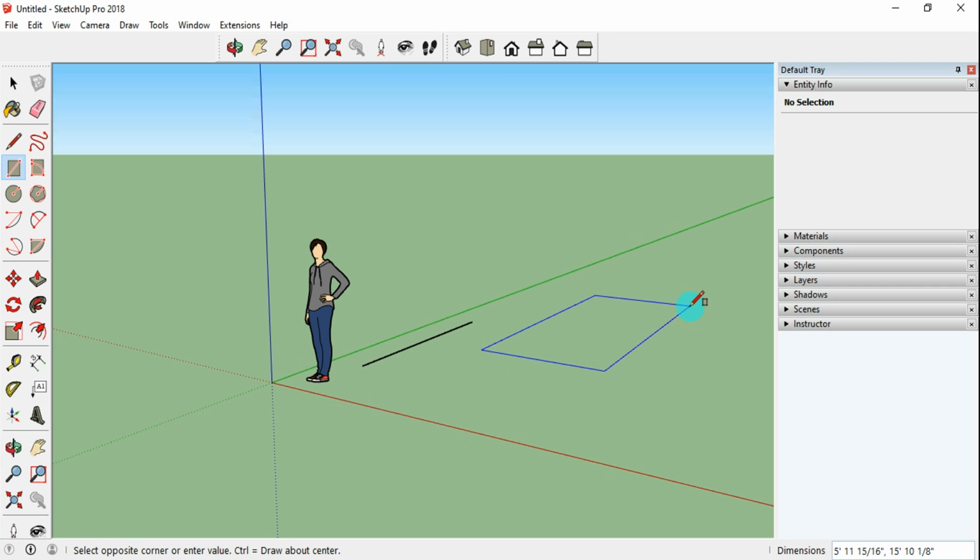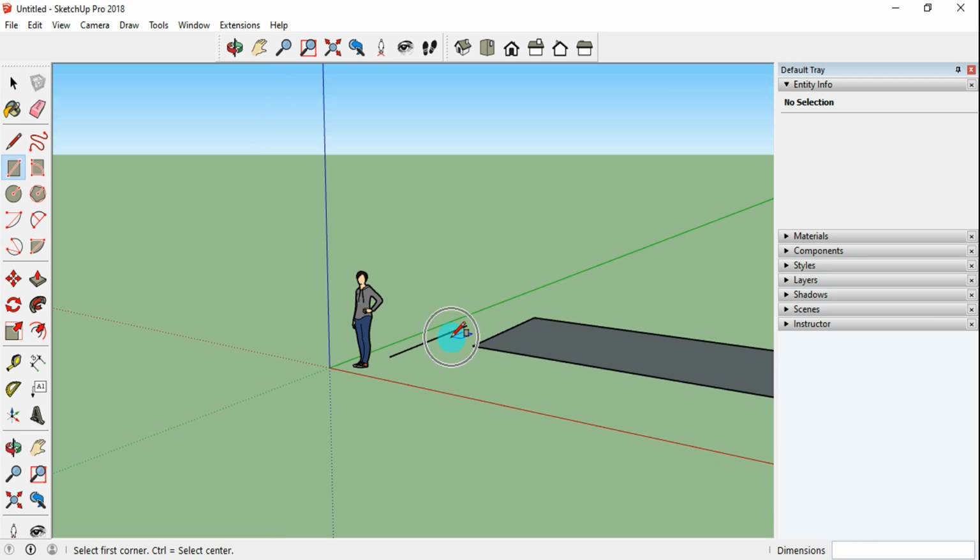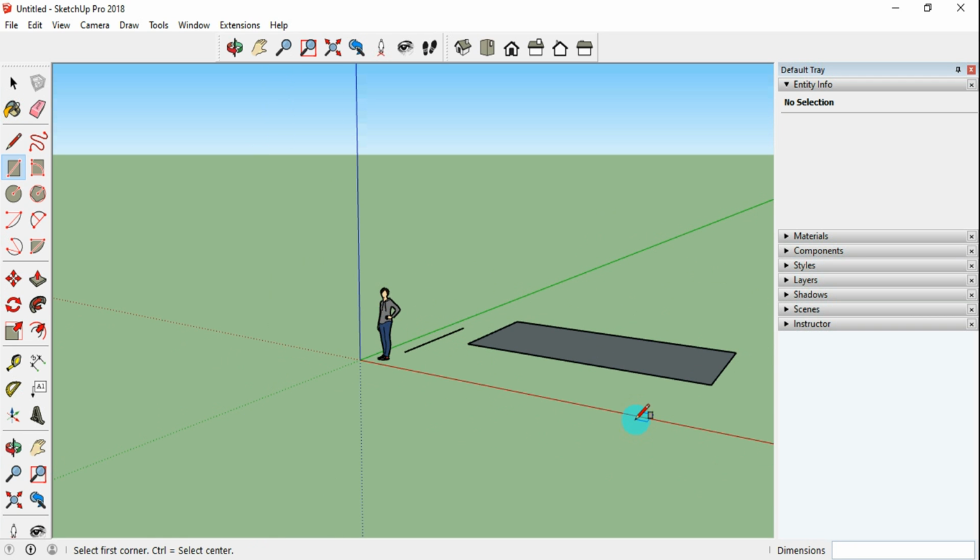Or else you can give the length and width value. So for example, I want to give 20 feet comma 30 feet. I can give it in the measurement bar, like here at bottom right we are going to get the dimensions, okay. So just define the values 20 feet comma 10 feet and enter. We are going to get the rectangle of the given dimensions like this, okay.